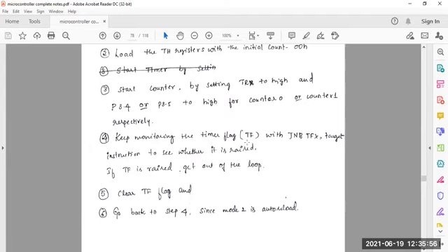That is nothing but a pin on the TCON register. Again, it is pin 3.6 and 3.7. Okay, pin 3.6 is for TF0, 3.7 for TF1. You can use the pin 3.6 and 3.7, or else just directly use TF0 and TF1. Okay, by using the instruction JNB TFX, where X stands for 0 for counter 0, 1 for counter 1.